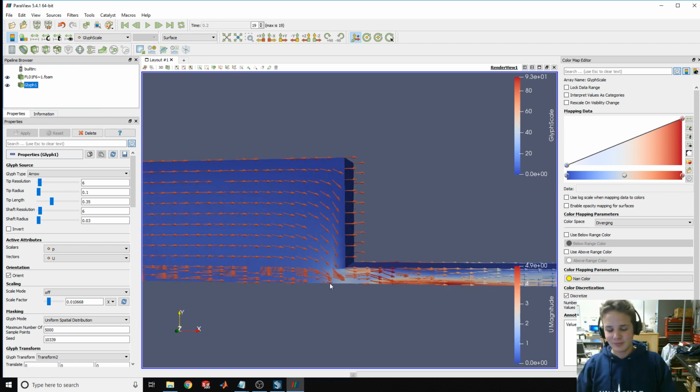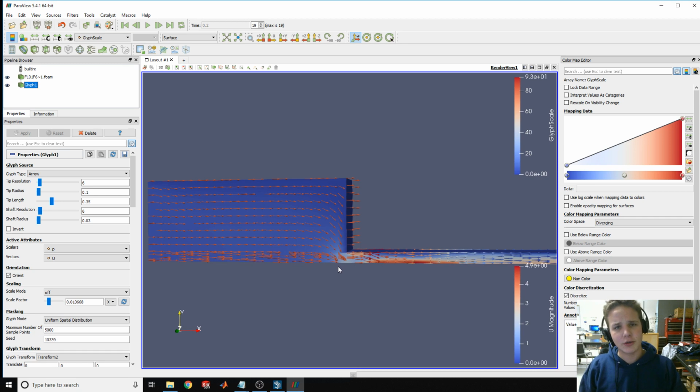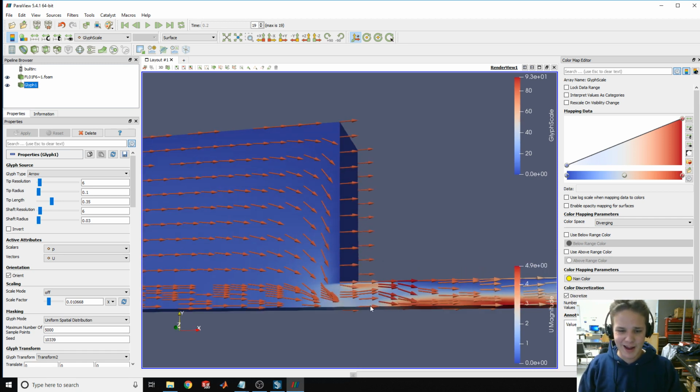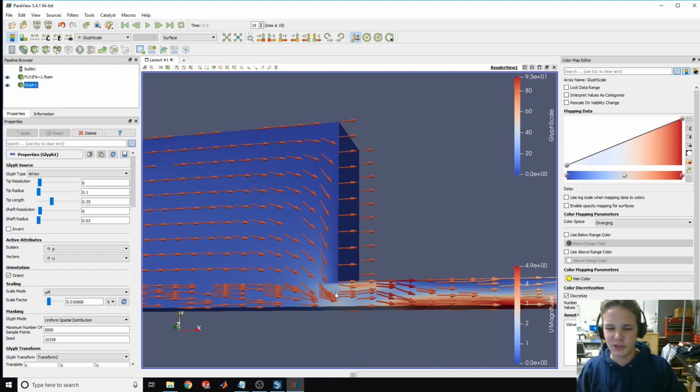Now, fluids is super complex, so whatever experience level you are, you should understand that there's not really a perfect way to solve anything. All this has error, and with error comes wrongdoing, so you have to make sure that you're not having too much error where whatever you're designing or engineering is going to mess up because of your simulation. So you have to make sure that the conditions you're giving it are correct for the type of solver you're using. And it's pretty obvious that I don't know if I trust this because it's starting to get a little more chaotic. I don't think pimpleFoam can really solve this.